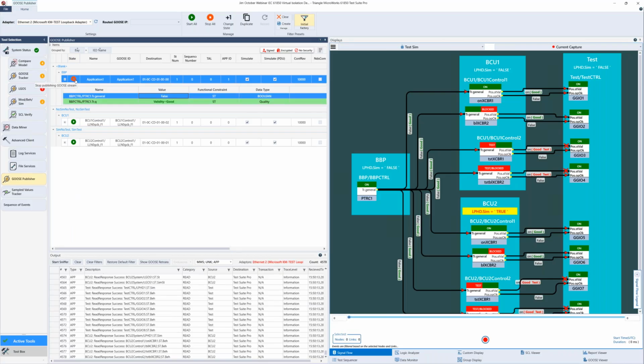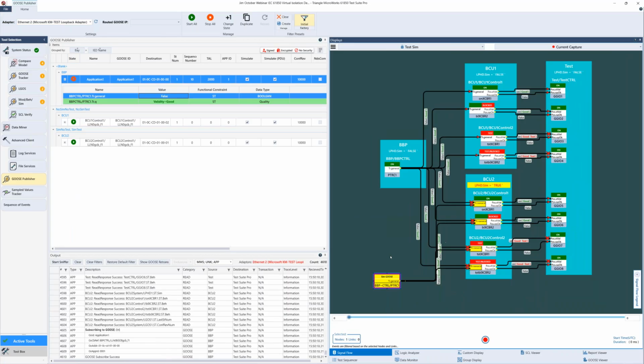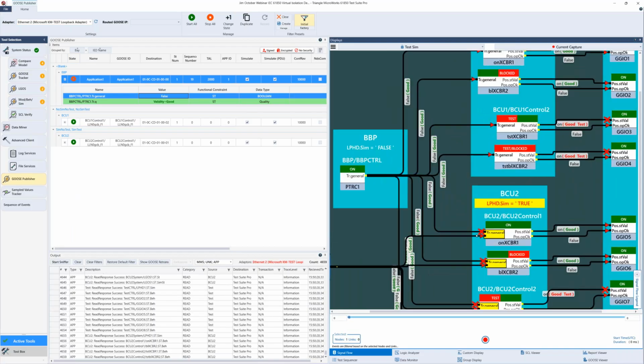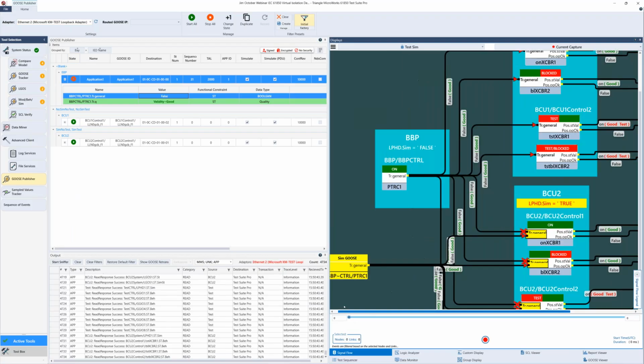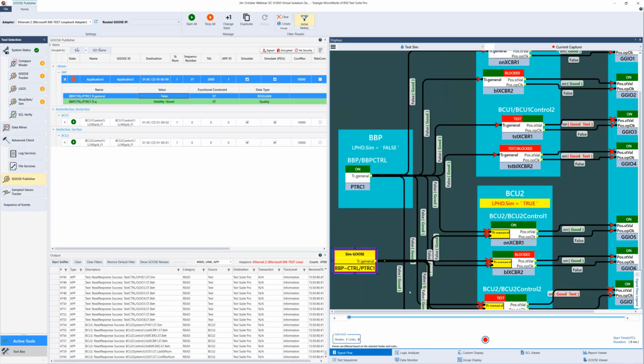So now we are publishing this message. And what we see over here now in the signal flow diagram is that there is a simulated message available. So we can put that here as well. We can visualize. And now when we zoom into the details here, you see it shows that it will not receive the normal reception message anymore, but it will now receive the simulated message down here that is coming from our test report that is publishing this as a test equipment.